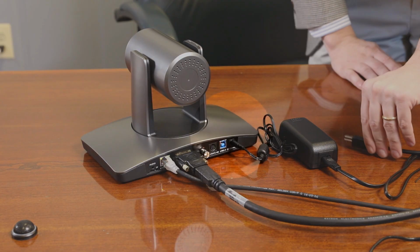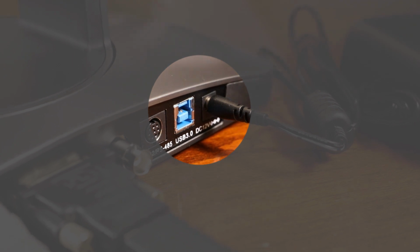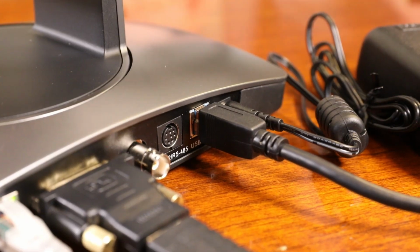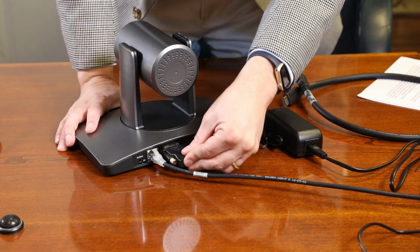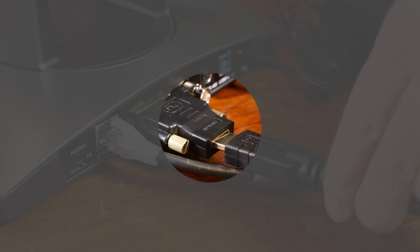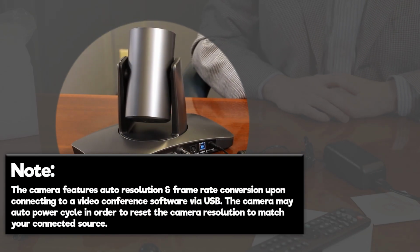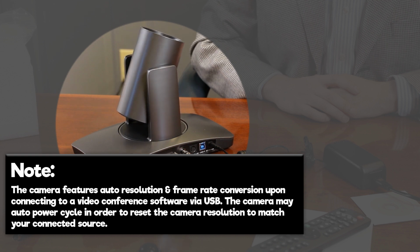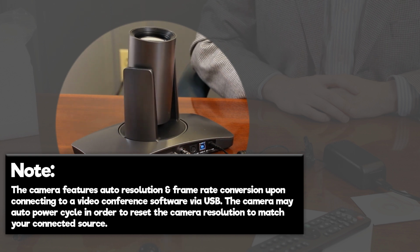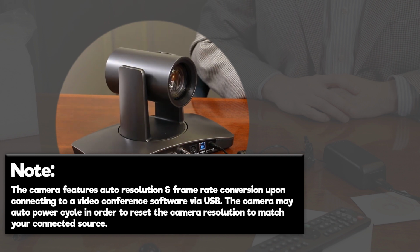You may want to connect your camera to a meeting room computer or in-room display. You can connect the camera to a computer using the USB 3.0 output, to any standard television using a DVI to HDMI cable, and to an SDI monitor using a standard SDI cable. Note: the camera features auto resolution and frame rate conversion upon connecting to a video conference software via USB. Camera may auto power cycle in order to reset the camera resolution to match your connected source.